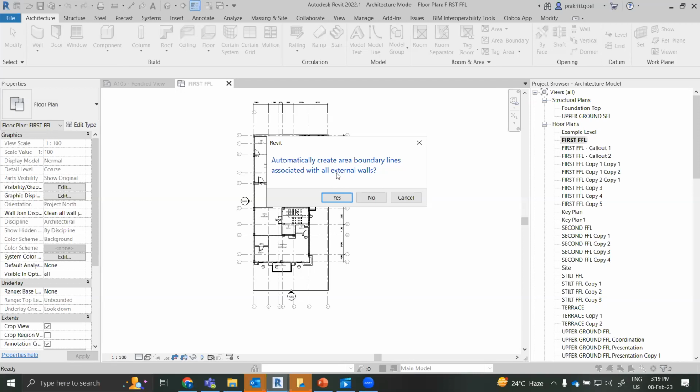But if you have a super built up area, then you can just provide that, right? Because we have separate areas like floor area, store area, building circulation area, this is not appropriate for that reason. But if you are going for super built up area, you can just go for automatic creation. But do remember, this follows the Autodesk rules as well as the foreign standards. So the boundaries will come at the center of the walls, not the exterior facade of the walls. So do remember that.